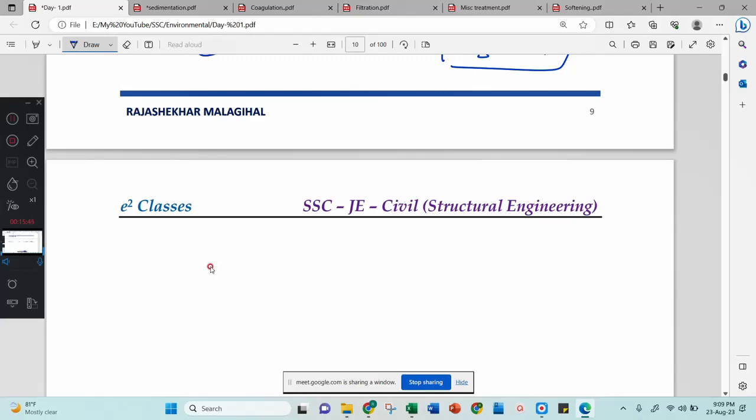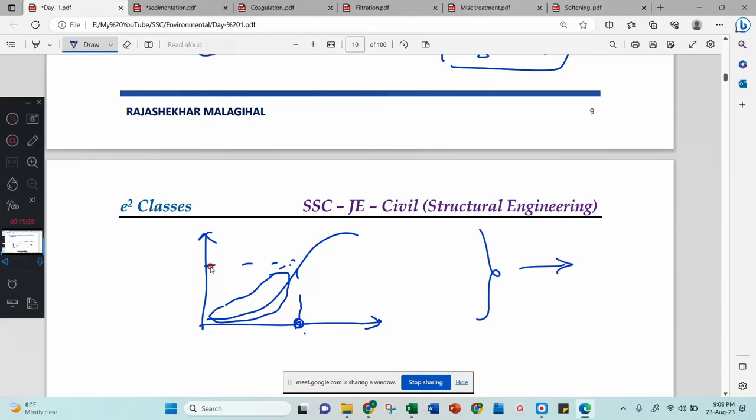No. Here that comes, you do sieve analysis and you make a graph, and after that you design your tank for some diameter d. Then you can ensure that this will be removed. There is a big procedure for that. In that procedure you will come to know the efficiency of the tank removing the particle size smaller than the design particles.